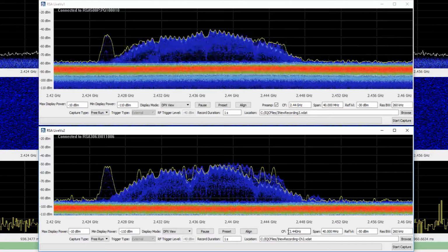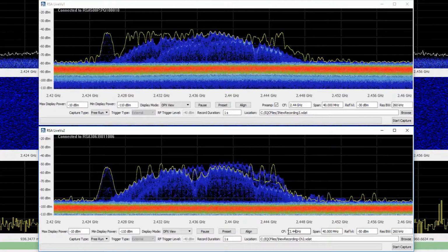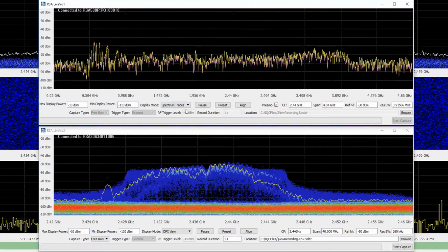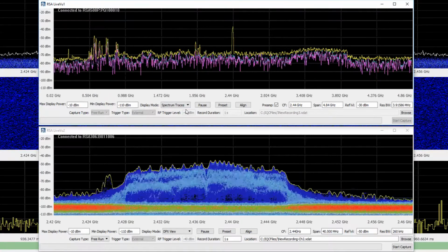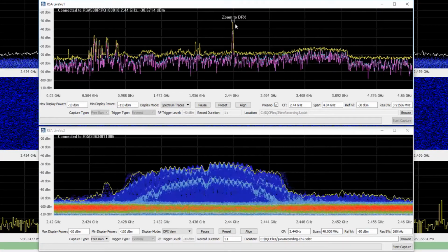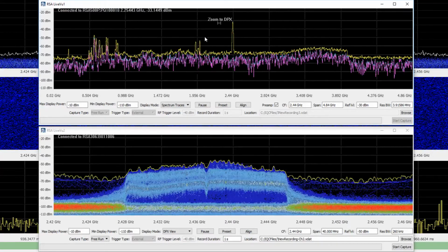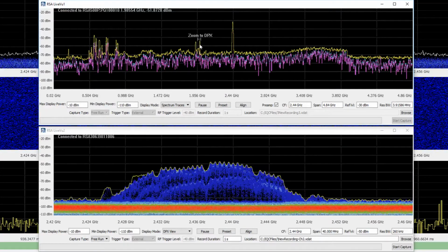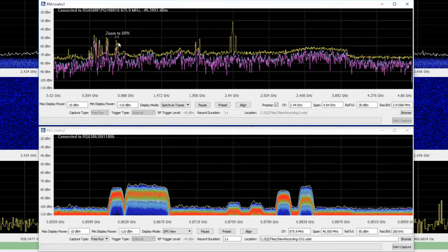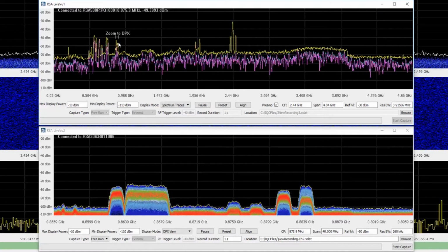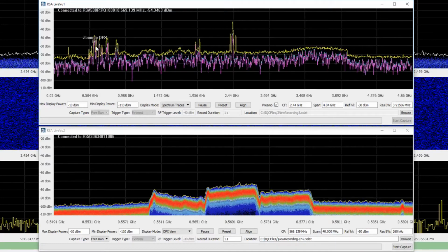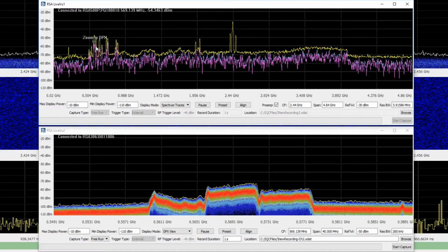Now let's show a really useful feature for when I'm searching for an unknown signal or monitoring a certain bandwidth. To do this, let's switch the display mode on RSA LiveView 1 to the spectrum traces. Now you can see a really wide bandwidth. At this point, we're looking at about 4.8 gigahertz. Now we can simply use our cursor and zoom in on different signals that we see. This allows us to see a very broad bandwidth in one display and narrow down to take a closer look in the other. You can change the span, reference level, and bandwidth as needed for each of these frequency locations.